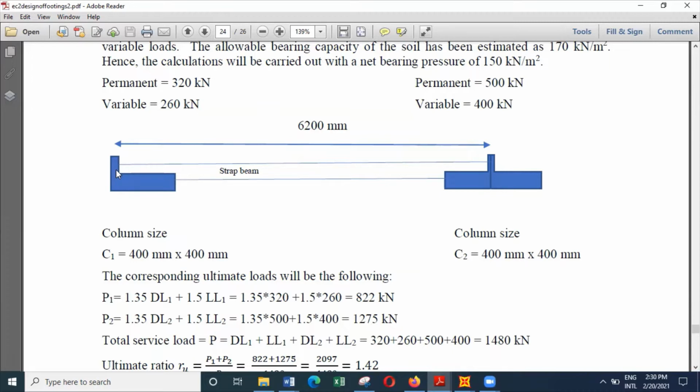So, the moment you select some approximate values for the bases, these are not finalized yet, but we have some idea that an eccentricity around 0.7 may work, which means an eccentricity of about 0.6 also might work. So let's start with an eccentricity of 0.7, and if it gives reasonable values, we can stop the calculation. Otherwise, we'll have to do another trial.